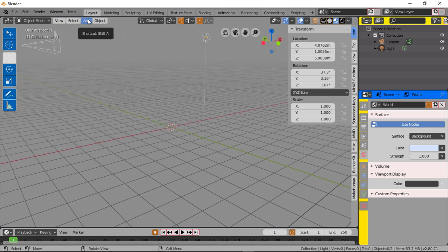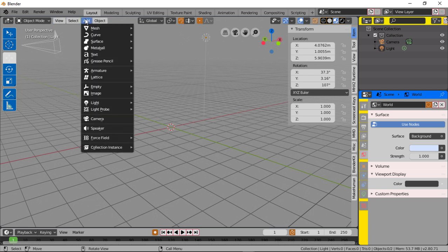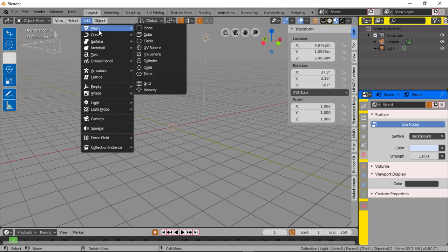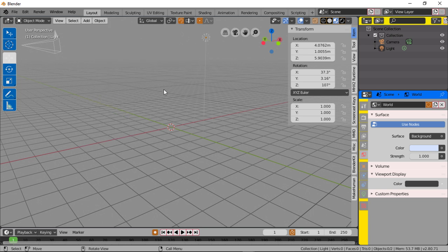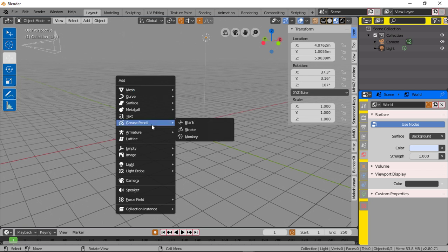For those who are brand new to Blender, now we're going to use this toolbar up here. Usually it's on the bottom, but the default is now set up to the top for Blender 2.8. We're going to go to Add. We're going to go to Text. So if you want to add anything, you can go up here and check all these different things. You can also use the Shift and the A key, and it does the same thing. So I'll do that real quick. Shift A, and then go to Text. See, it says a little A icon and Text.